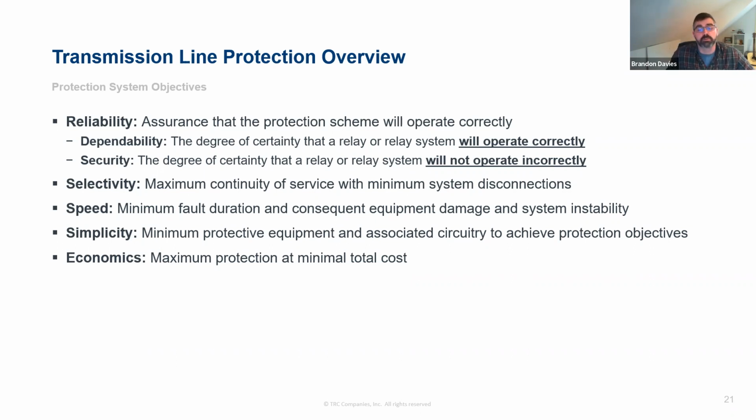And actually, when you get to a BPS site, which is a bulk power system site, in general, it's all of our 345 kV stuff in New England, as well as some 115 or 230 kV equipment, there are some other regulatory requirements that require complete redundancy of everything. So you have to have redundant relays fed by redundant CTs and VTs, operating redundant trip coils in your breakers, fed by separate battery systems. It's complete.